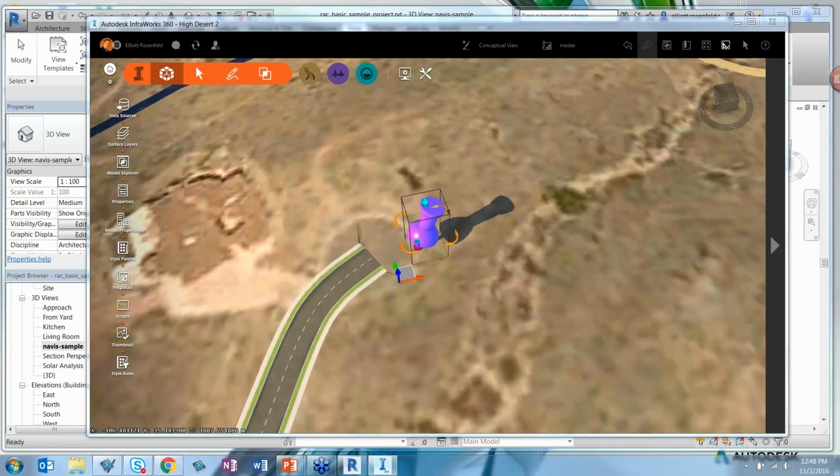Yeah, and in terms of Infoworks using an NWC file, not really. Navisworks is processing the RVT file or the FBX file that you import and converting it into the Infoworks data sources panel. So it doesn't strictly become an NWC. It does actually create one, because your desktop will have a copy. But you're not going to need to actually use that NWC file. You're not going to need to directly open it or really worry about that.